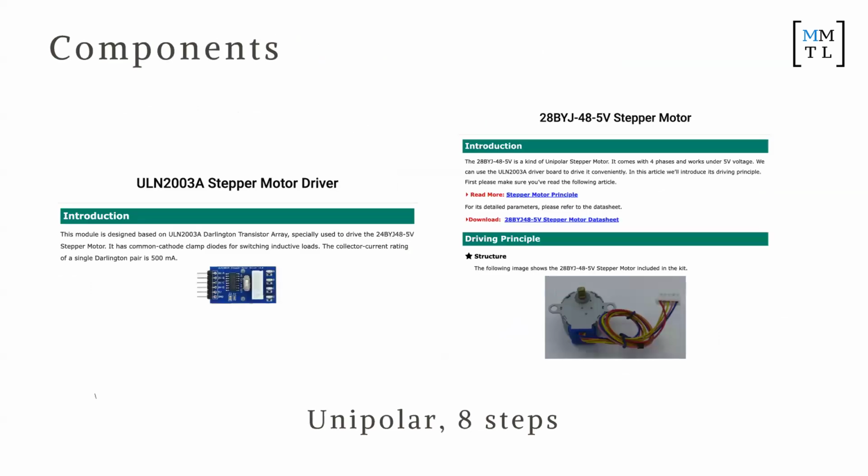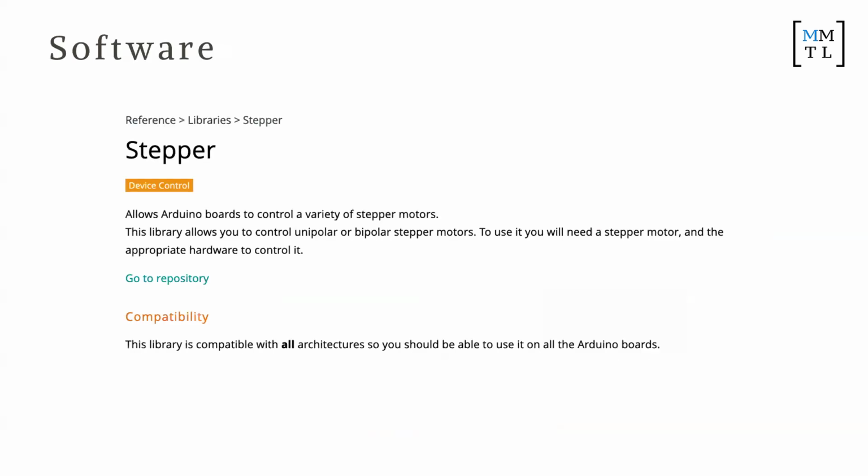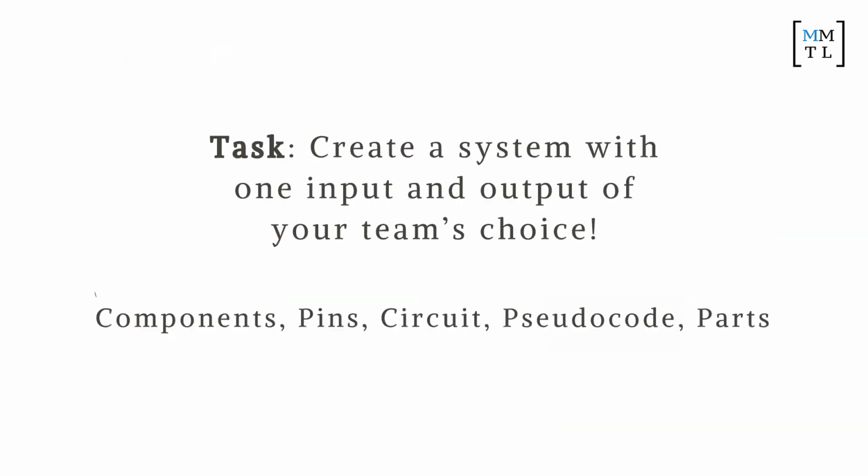Again, same sort of principles. In order to work with a stepper motor, you need to have a stepper motor driver. It's one of those components where you need extra current or extra voltage requirements, extra stability in the current and voltage, and so you have to use what's called a stepper motor driver. Arduino also has a stepper library that makes it really easy to use. I think CJ here has been using that, which is really cool.